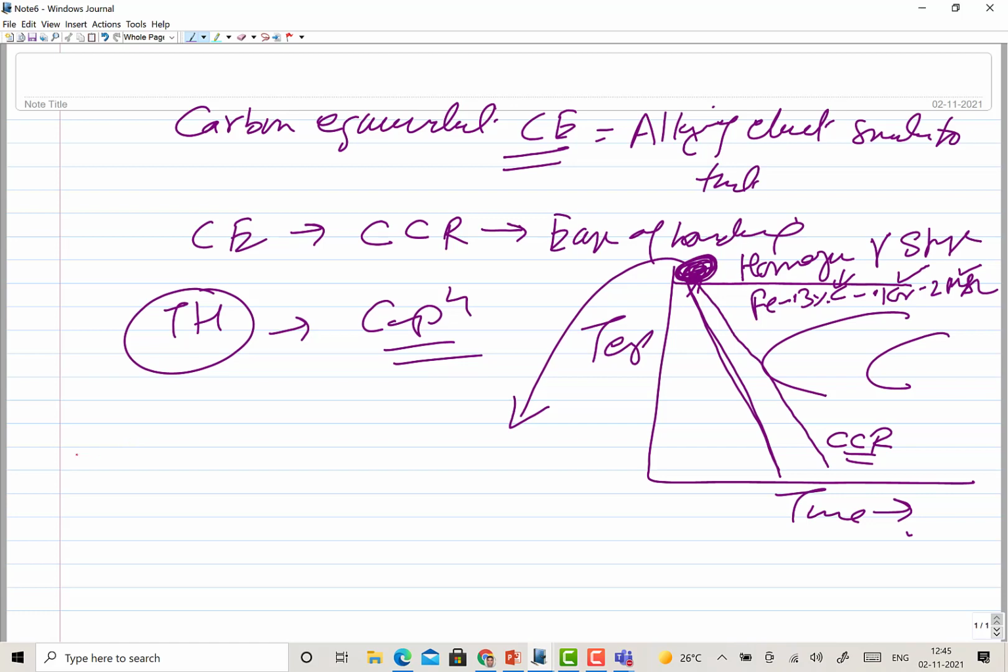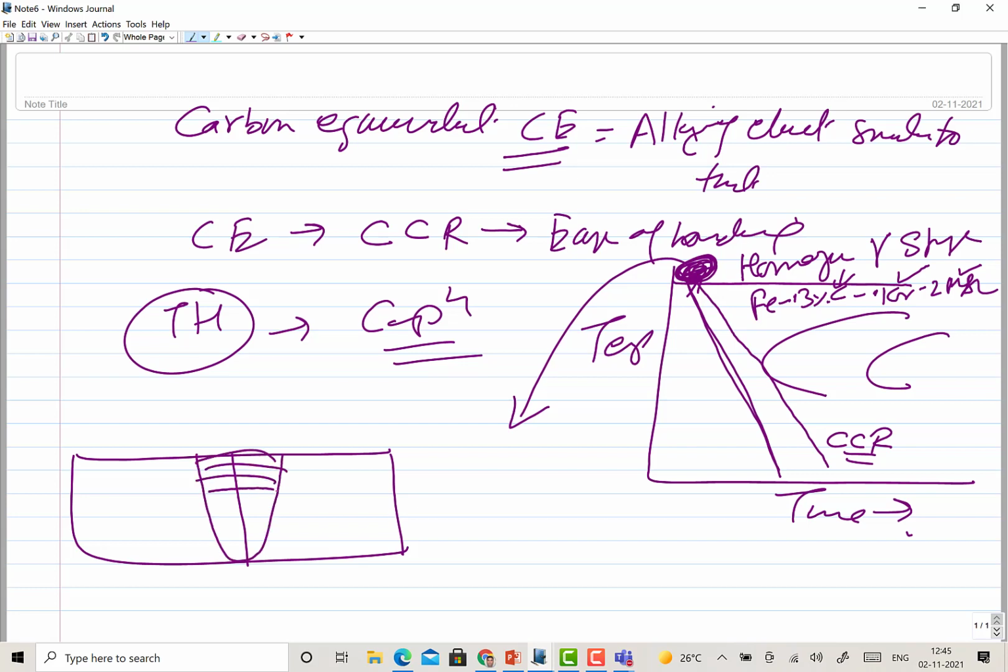In welding, let's say these are the two components. This is the section that you have fused, or deformed, for developing the joint. But the zones which have been heated nearby, say just for 2 seconds to 800 degrees centigrade, or heated to 1400 degrees centigrade just for, say, 1 second.